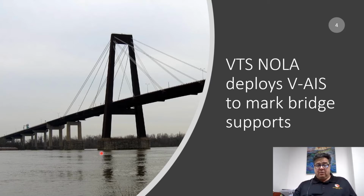So in order to help you see where the bridge piers are, the Army Corps of Engineers puts buoys out in front of the pier. We call them fog buoys. And they do show up on radar. And they're generally supposed to be in line with the pier. So when you're coming down the river and the pier comes up on the radar, you see these buoys in front of it. You know where the bridge pier is.